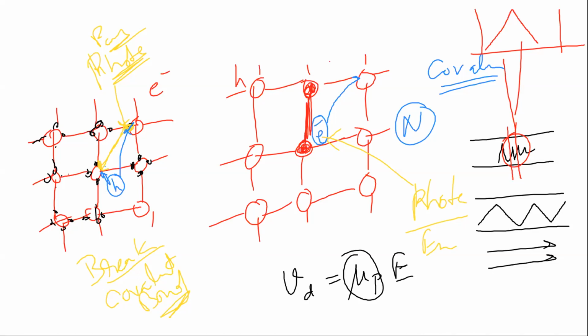There are architectures of 6 transistor, 8 transistor. Everywhere we are using NMOS, because historically, from the mobility point of view, they are fast. So in memory, these structures are more or less in terms of NMOS. Nowadays it can be PMOS, but traditionally we are using NMOS. That's the reason we are using NMOS.